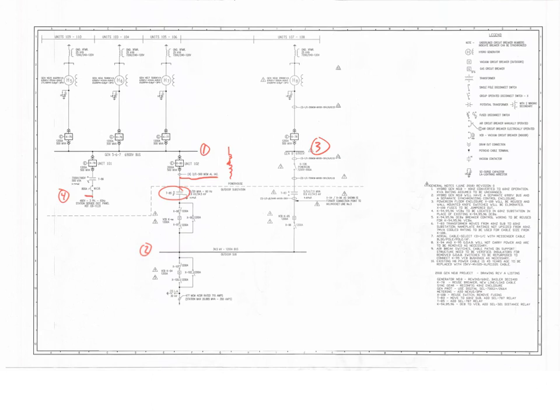How's it protected? MCCBs, right? What do those letters stand for? Molded case circuit breakers. Okay? So molded case circuit breakers are fairly important in terms of protecting some of the smaller loads. What's a smaller load? Well, obviously your house, 15 amps, 20 amps, maybe 30 amps for a 2-pole breaker if it's a dryer, 50 amps if you're getting to a range.